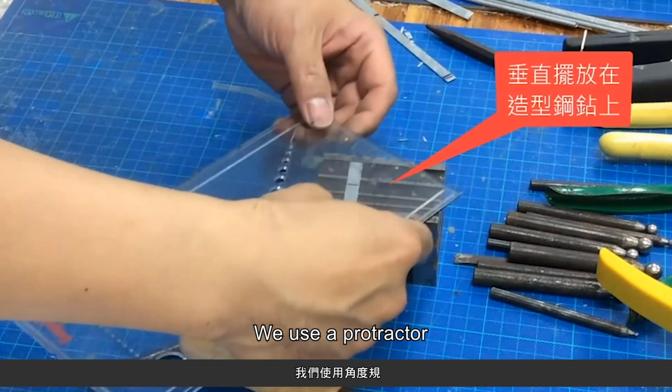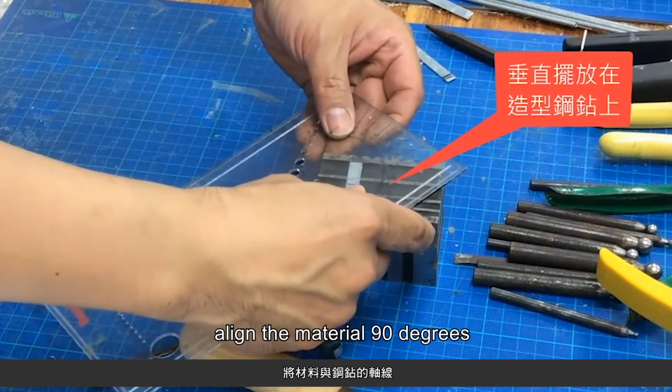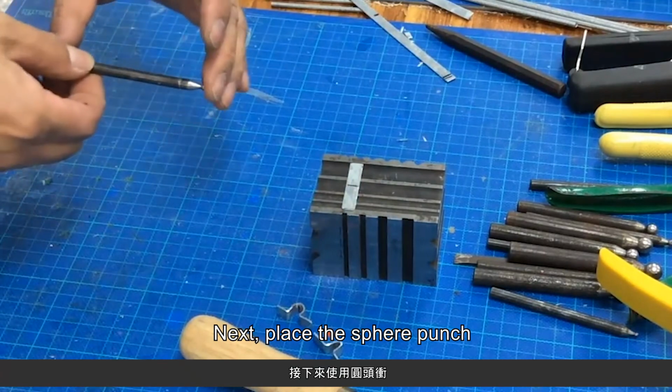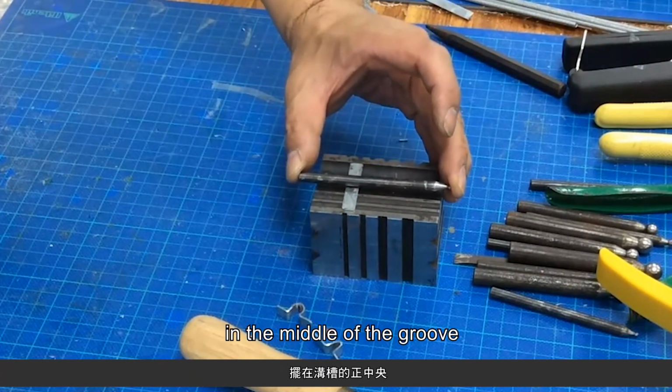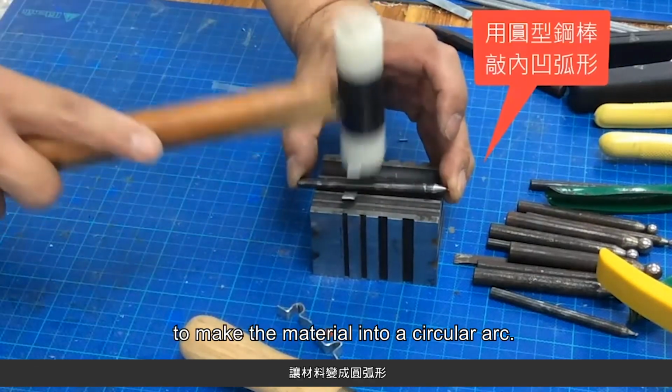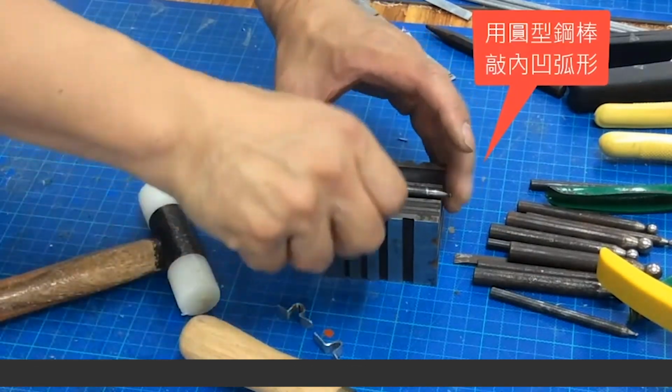We use a protractor to align the material 90 degrees to the axis of the anvil. Next, place the sphere punch in the middle of the groove and hit it with a PVC hammer to make the material into a circular arc.